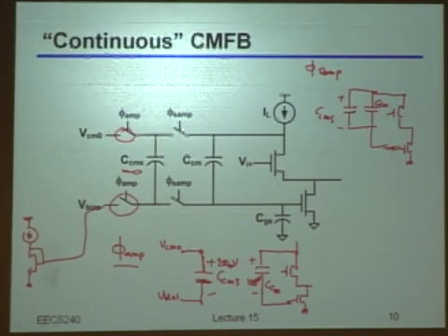If I start 200 millivolts from one side and 100 millivolts on the other, they will share the charge, right? So I will sit in a spot like where? What is the range? In between 100 millivolts and 200 millivolts, right? So that means that gradually, in a graceful way, I'm getting there, but I need some time, and I'm still transferring charge from my reference source to the amplifier. And at the end of the day, I will settle to the common mode that I want.